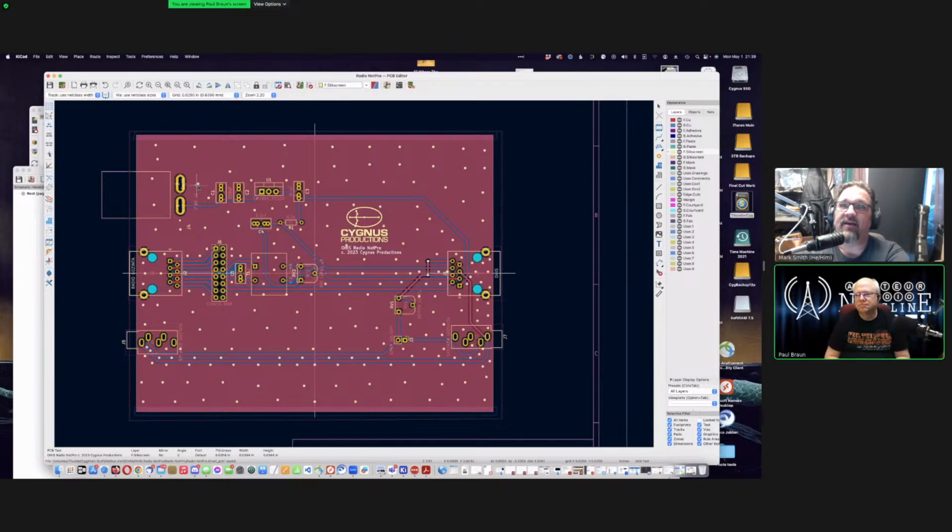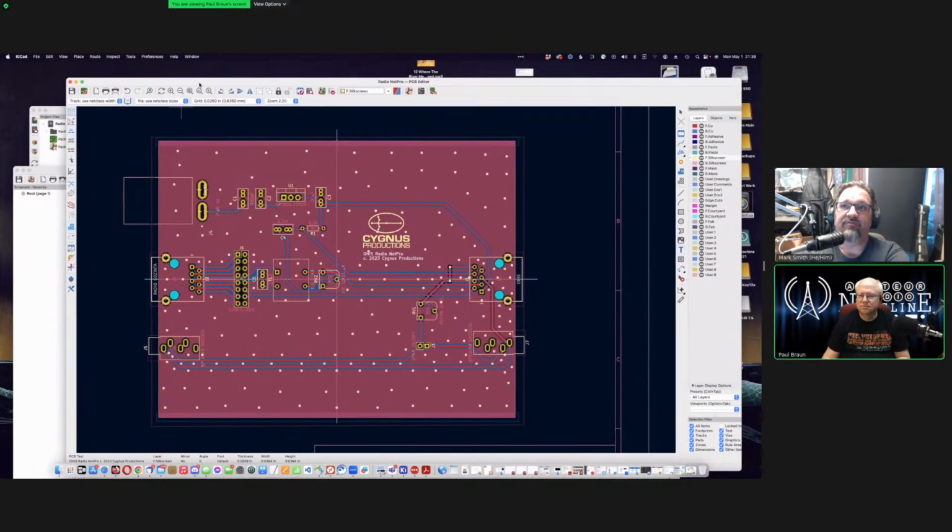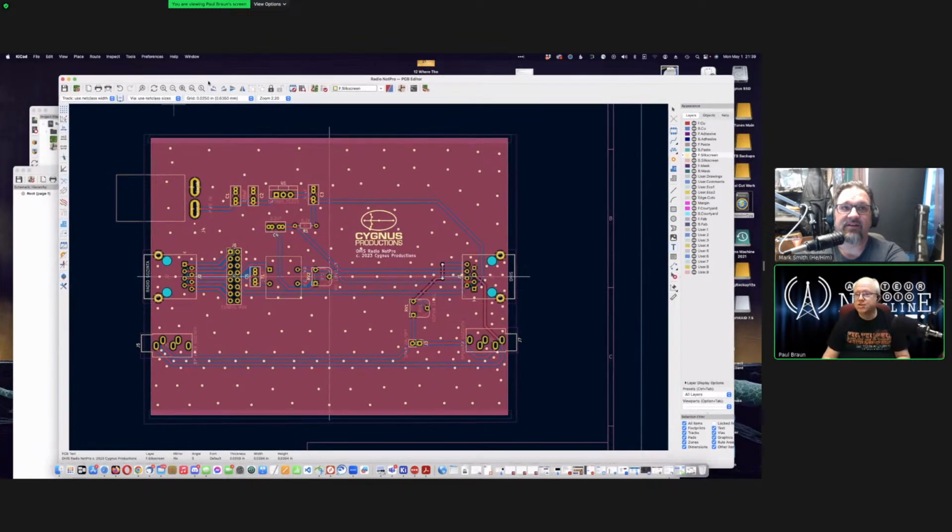Yeah, that would be a good idea. Dropping a diode on there is pretty easy. I don't know if you want to put a fuse in there as well, or assume that you've got a fuse in the Anderson power pole distribution. I'll let you decide whether you want to do that. Well, yeah, because my power for this is all coming off of the Workbench one power distro, so it's all fused.